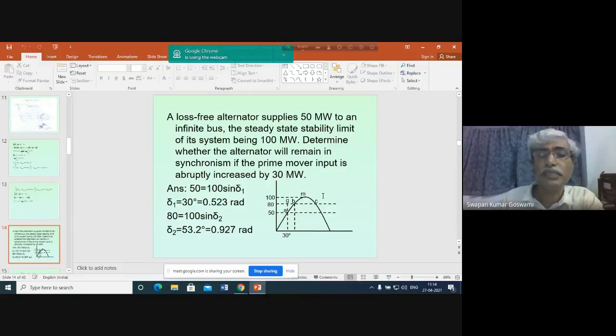If the speed is above synchronous at this point, it will go on becoming higher and higher above synchronous speed. It will continue to increase. So there will not be any chance for the generator rotor to regain synchronous speed. Therefore, synchronous speed must be restored at this point or before this point is reached.